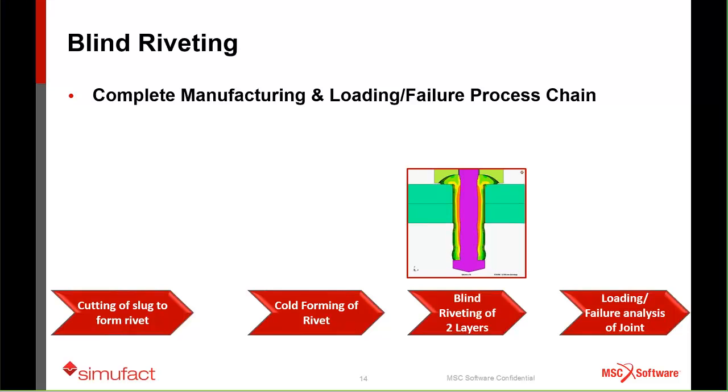I'll play this again. Here you see how this is formed to connect the two layers. I'm not showing it on these slides, but a study was done to simulate this process with the stresses that come from the forming process of the rivet and without them. For this particular example, it was crucial for the correct result to take into account the stresses coming from the forming process.